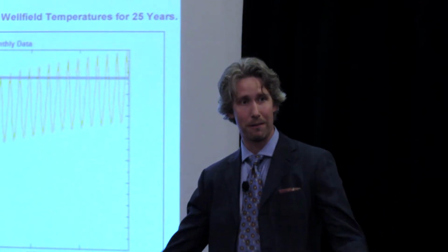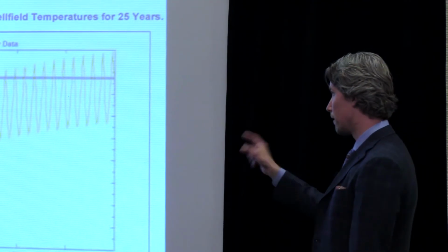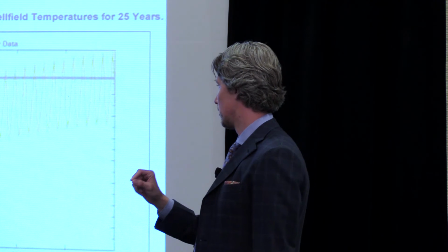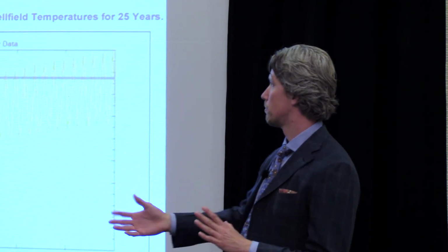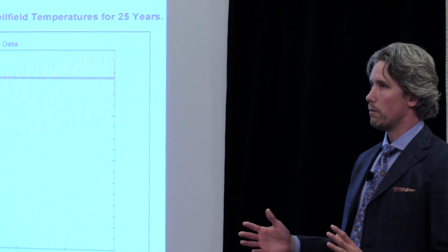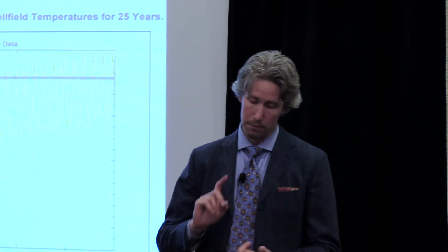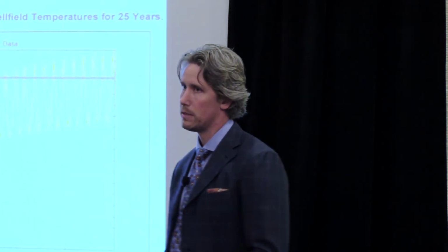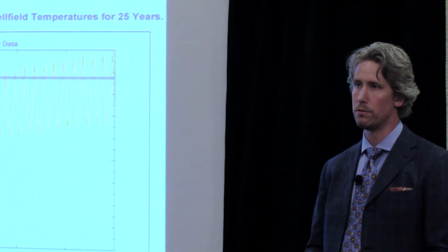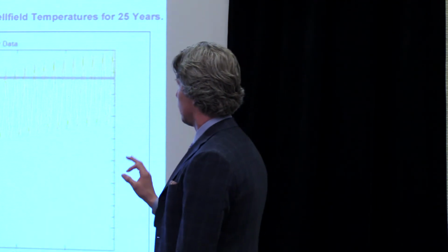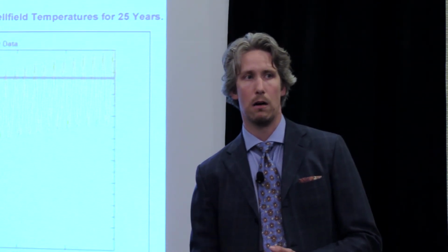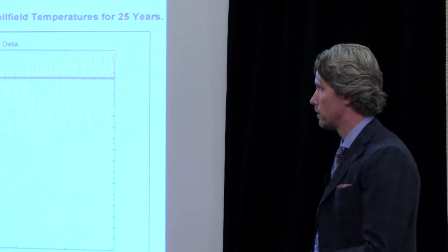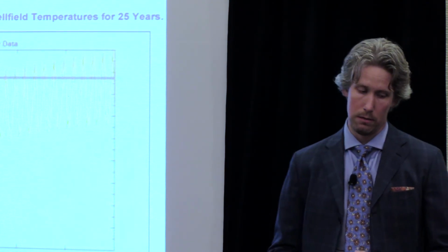So that was a really cool engineering thing, right? We were able to get our well field simulator, on the very first try, I might add, to tell us that the well field was going to hit the actual temperature we were seeing 10 years later. We were then able, through the same process of exporting block loads from the energy model, to evaluate some different options, including adding more wells to the system or adding a cooling tower, but also some more nuanced things like adding tinting to the windows, other strategies that reduce the annual cooling load. Not only could we tell the client how much energy they would save, but also what the effect on the long-term well field temperature was. I thought that was really cool, because that was actually more important to them than anything else, really.